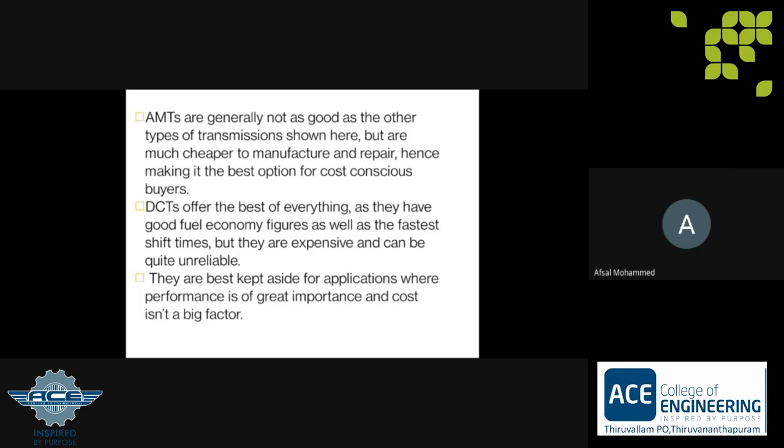Okay, so DCTs. DCTs actually are a very good transmission system. However, the only problem they are facing is reliability, and they actually offer the best of everything. DCT cars offer better fuel economy than their manual counterparts, and they also shift incredibly fast, under 100 milliseconds, as I've already told. This means they're offering everything except reliability. However, in a country like ours with a tropical climate, they are not a very good option to go for.